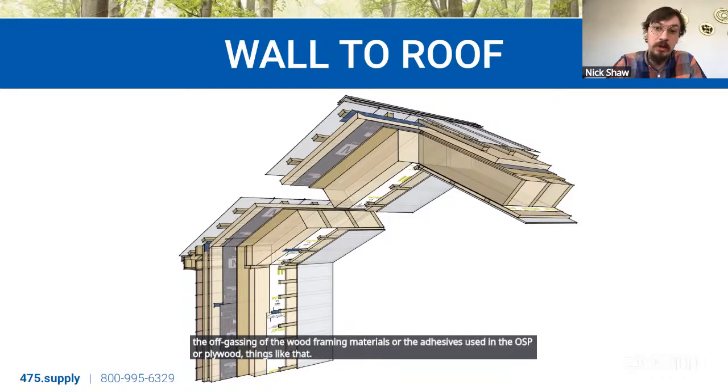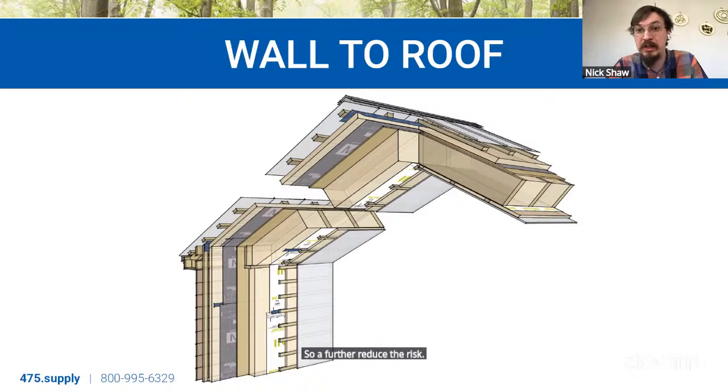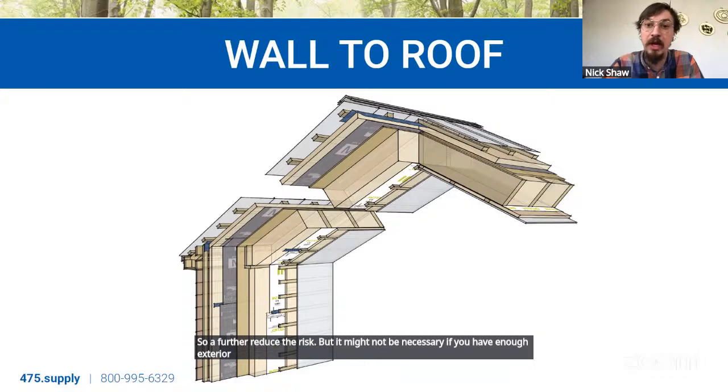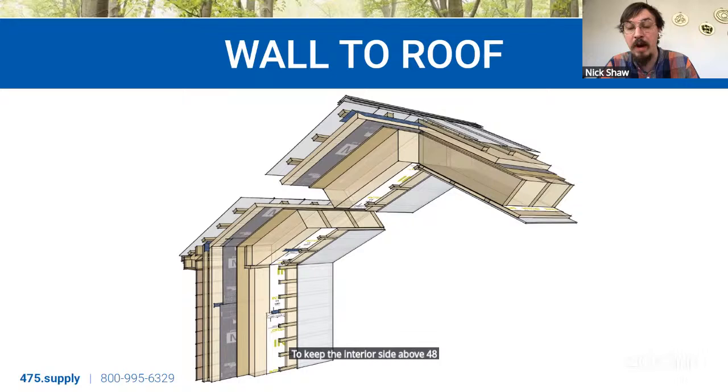So it'll further reduce the risk, but might not be necessary if you have enough exterior insulation outboard of that sheathing to keep the interior side above 48 degrees Fahrenheit year round.